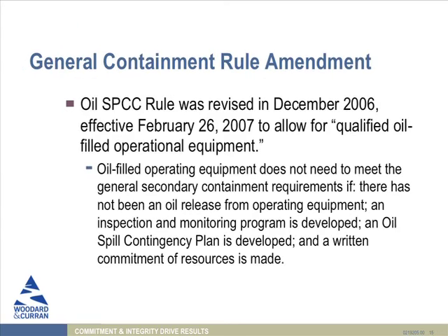Now, there's been a revision. This was one of the December 2006 revisions to the SPCC rule that instituted this new thing called qualified operational equipment. Because of the scenario where sometimes it's very difficult to try to do that. And I think the transformers are a good example. If you have a transformer just on a concrete slab in a parking area, a couple feet away you've got a catch basin, there's not a lot you can do to prevent a potential release from getting to that catch basin.